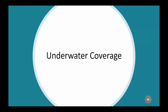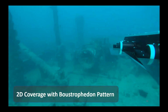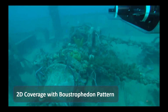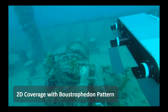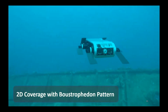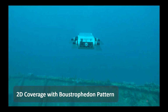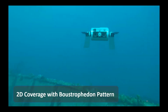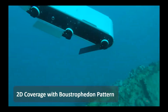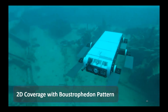Now, let's talk about underwater coverage. One thing that we have observed when doing experiments in underwater environments is that doing just a simple boustrophedon pattern that I talked about in the first part of my presentation might not be feasible in the underwater environment. One, we for sure don't have any GPS information. Two, even if we have state estimation algorithms, they are going to be failing most of the time. So how can we still perform some coverage of the environment, not relying on state estimation and using minimal computation and minimal information from that environment?